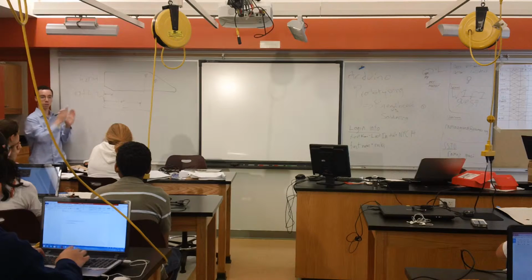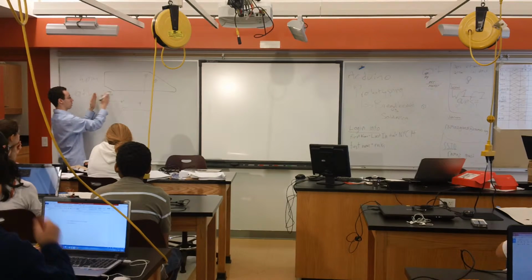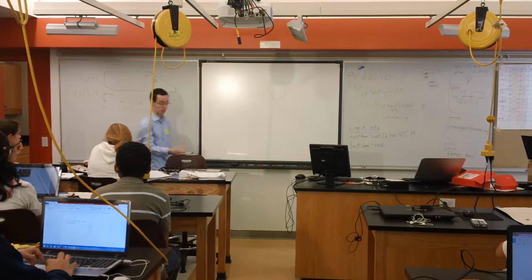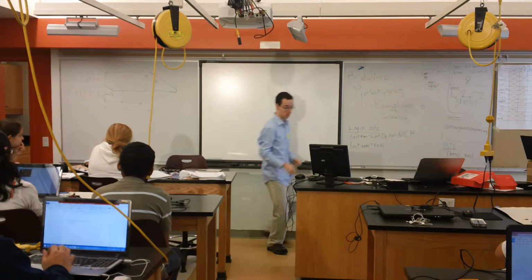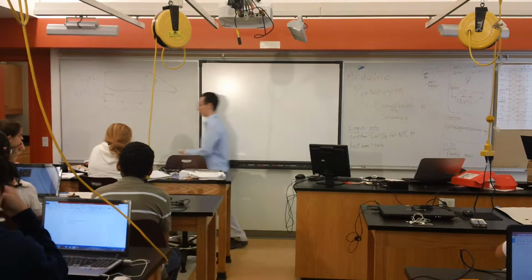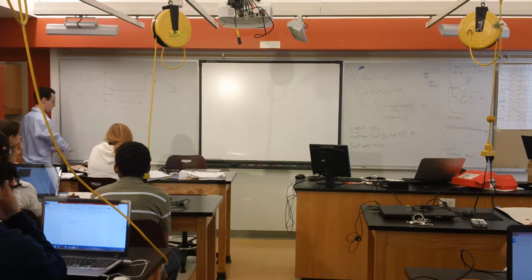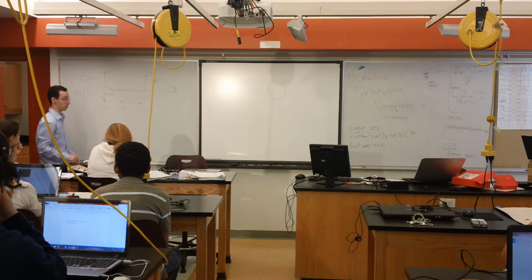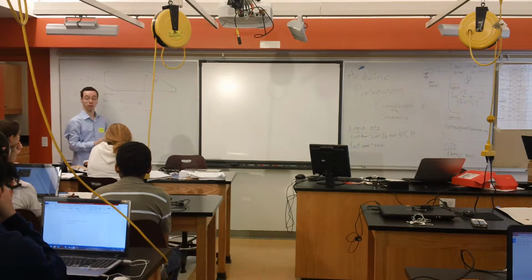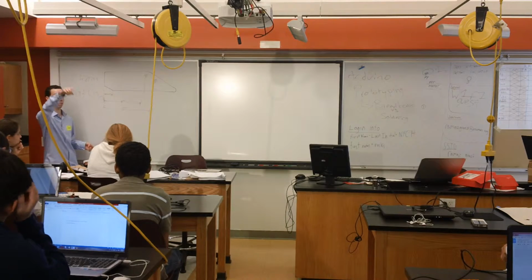How one is a chain of dimensions showing this is this far from this, so that's kind of like me saying, I take 2 steps over here and I'm at the chair, then I take another 3 steps and I'm at this computer here, and then so on. Whereas datum dimensioning would be saying, okay, from the edge of the board here, I have to walk 2 steps to get to that, or 5 steps to get to that, or 10 steps to get to the end of that. That's the difference. Yes?